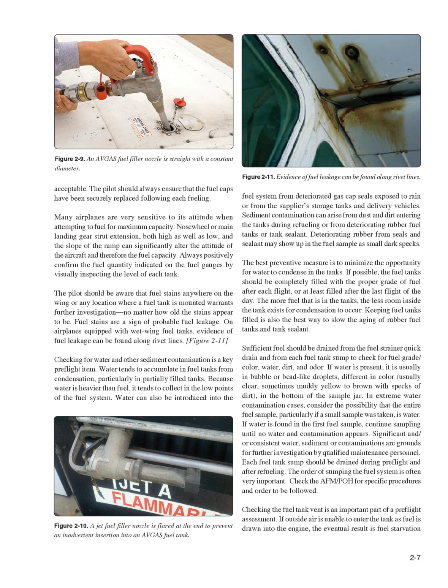If possible, the fuel tanks should be completely filled with the proper grade of fuel after each flight, or at least filled after the last flight of the day. The more fuel that is in the tanks, the less room inside the tank exists for condensation to occur. Keeping fuel tanks filled is also the best way to slow the aging of rubber fuel tanks and tank sealant.